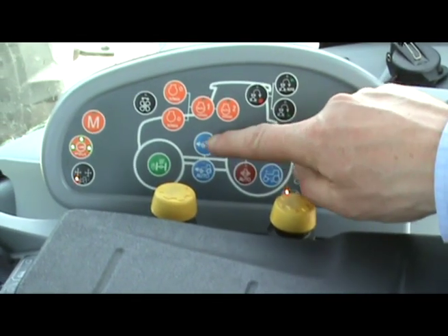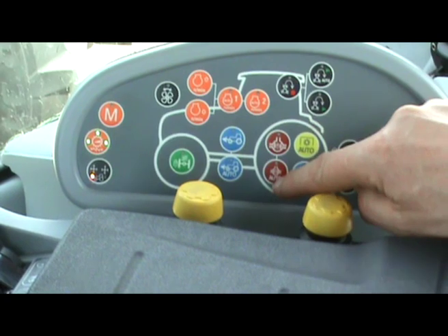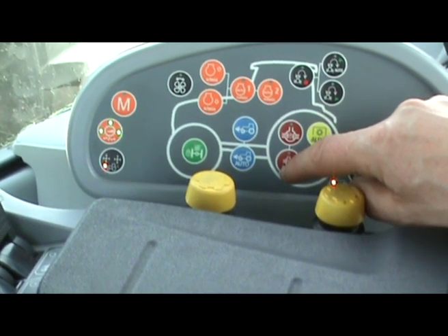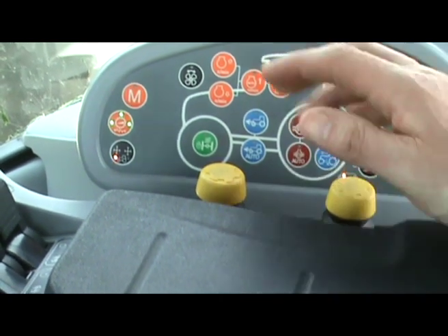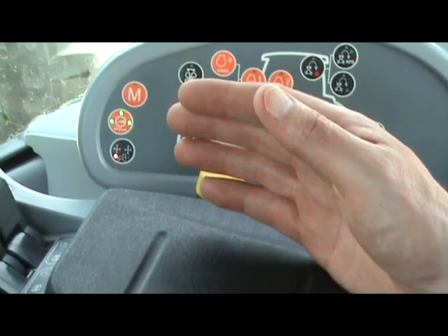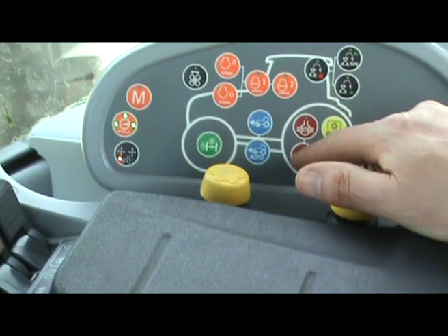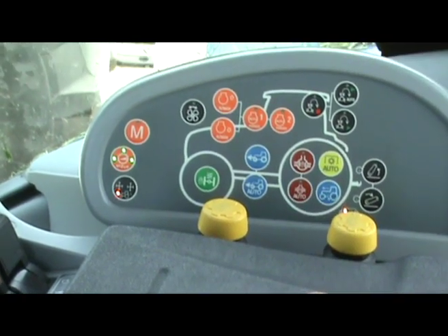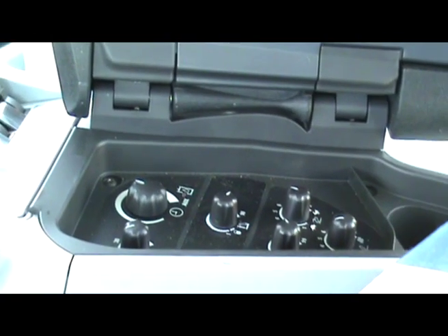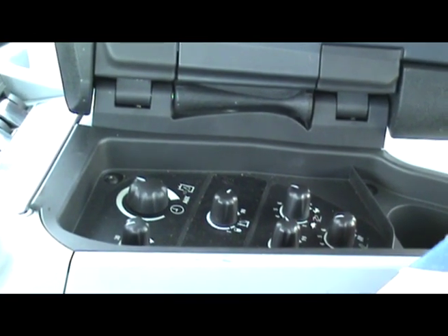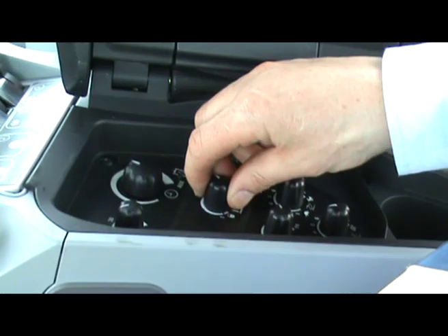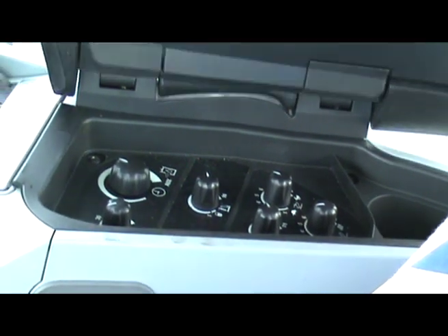And then the forward driving diff locks are controlled either manually, or they've got the New Holland so-called Terra lock on there, which is a steering angle sensor. So it's all controlled. When you come out to the end of the row of the field, turn the steering wheel, forward drive will come out and the diff lock will come out, straighten up, and they go back in. And that's the main controls. Underneath the armrest we've got the hitch limits, so your height limits, rate of drop, wheel slip control, etc. Usual hitch limits, all done on the dials under the armrest.